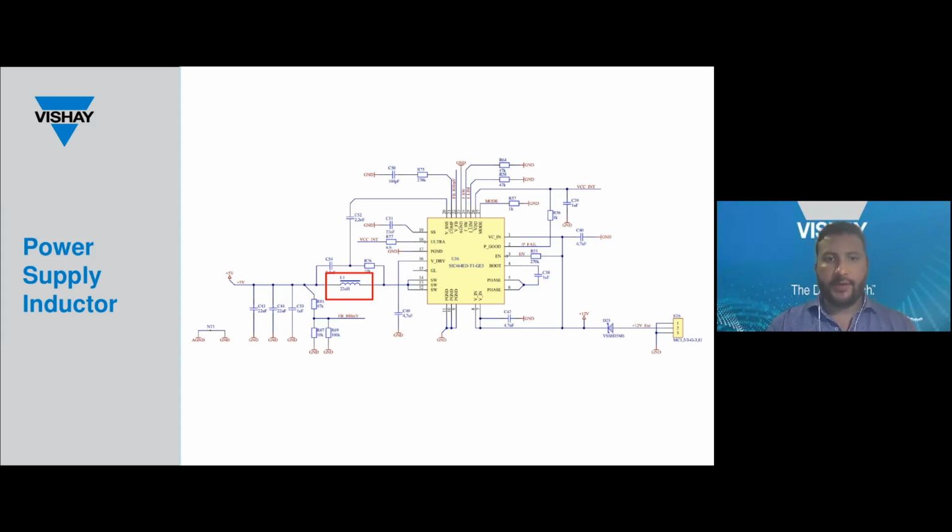So I was mentioning a storage inductor. Here you can see it in the schematic. In this case, a Vishay IHLP 2525 with a 22 microhenry inductor was selected. And this was all selected based on the microbuck datasheet requirements.